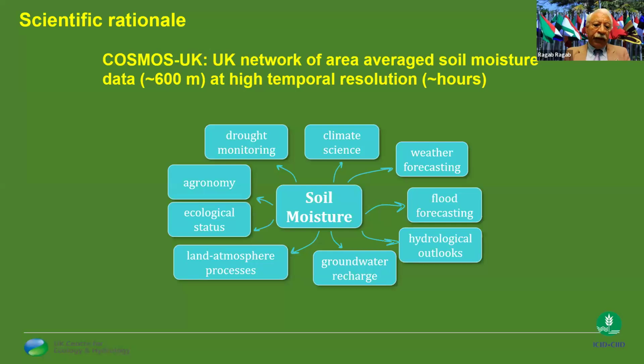If your soil surface layer is saturated, and you have a rainfall event expected, you are highly likely to get a runoff. If you are a reservoir manager, you have to pay attention and maybe release some of your water through the spillway to account for the oncoming runoff.